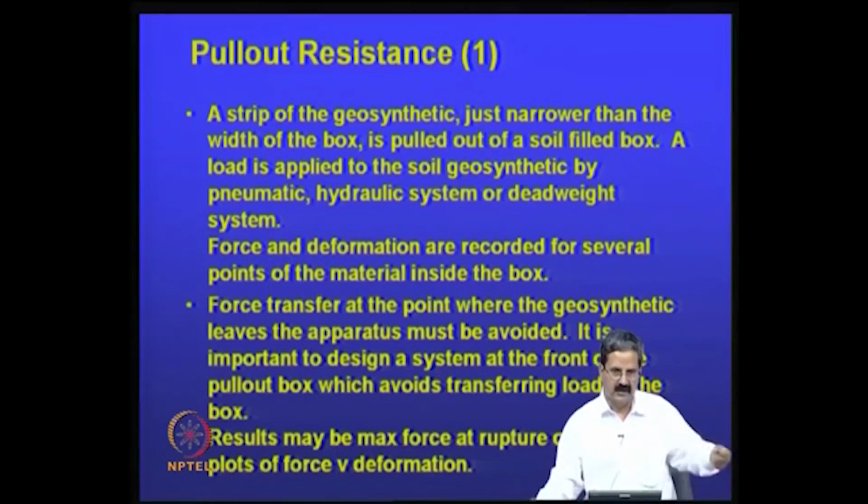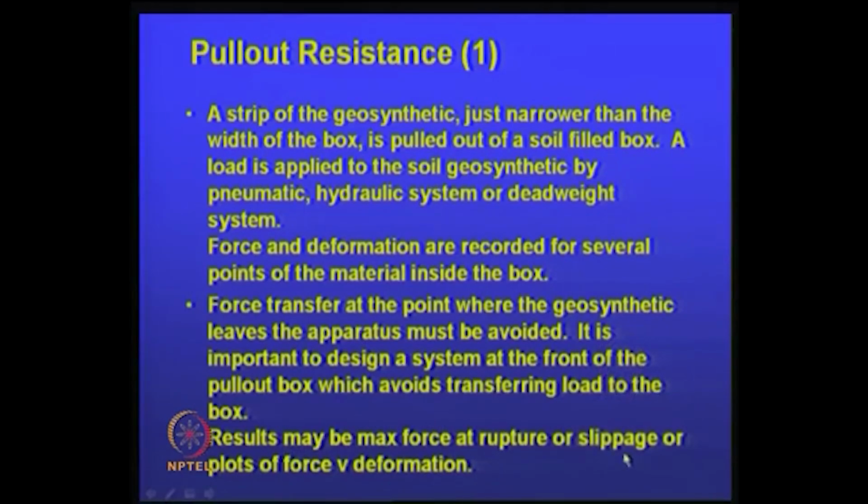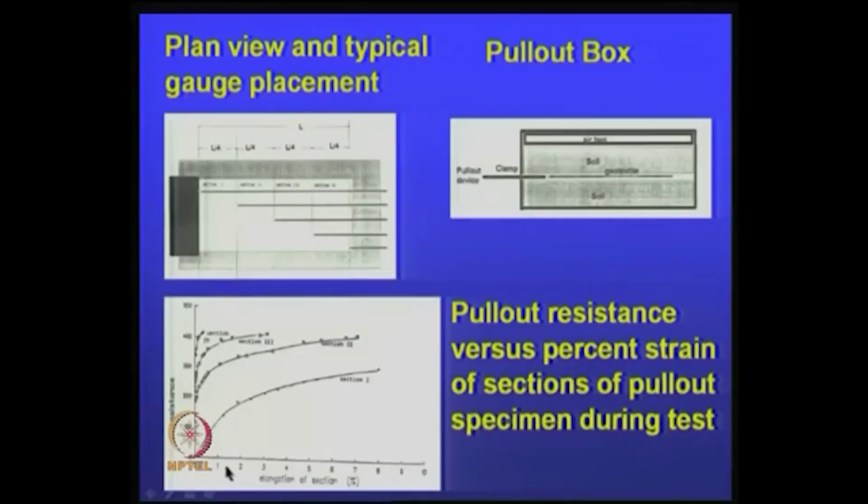You pull out a geosynthetic material, or even, as I will show you maybe in the next lecture, a soil nail, and you try to pull out the material and calculate its resistance. So, that is what we do. We plot the results in terms of how many mm it has come out and what load it has taken. So, force versus deformation are recorded like this, the elongation and the different forces.